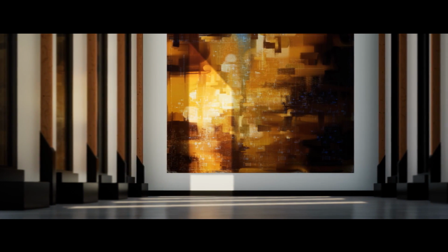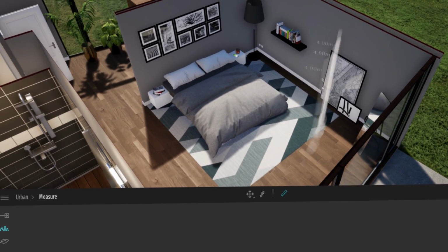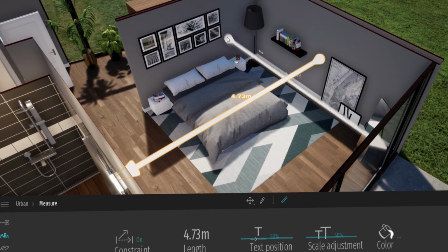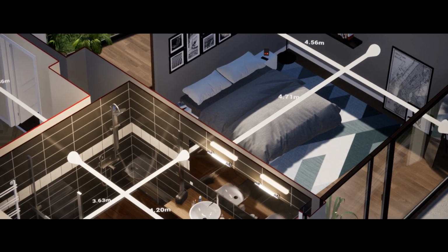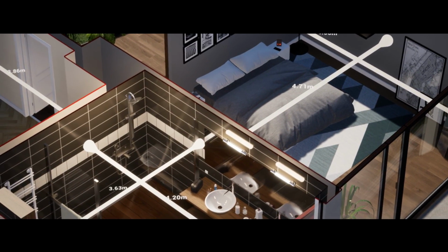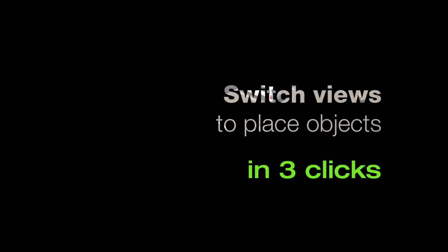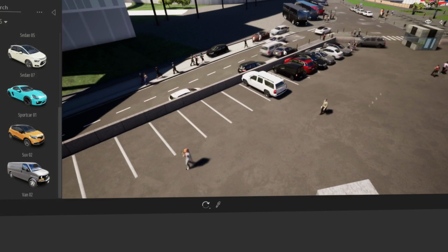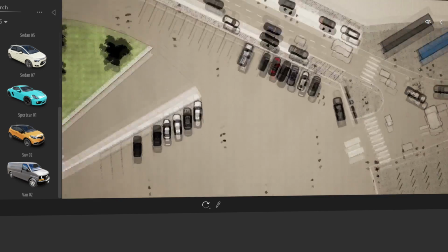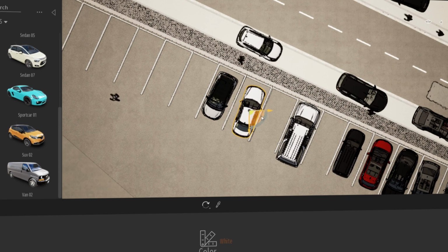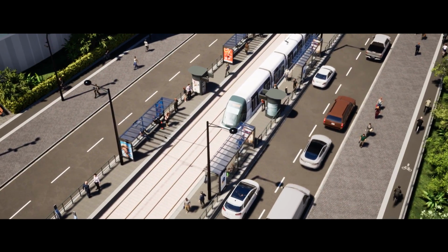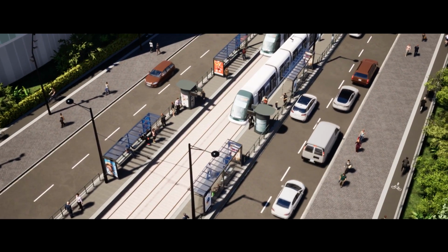If I import an OBJ model with textures and modify a texture in Twinmotion, will it remain modified if I import an updated model sometime later? How does Twinmotion resolve it? Twinmotion uses the material ID. So let's say you have imported your material with one texture. If you change this texture and replace it with another texture, the material still remains the same with the same ID. So if you update your project, we will keep the first material with the texture you have replaced.